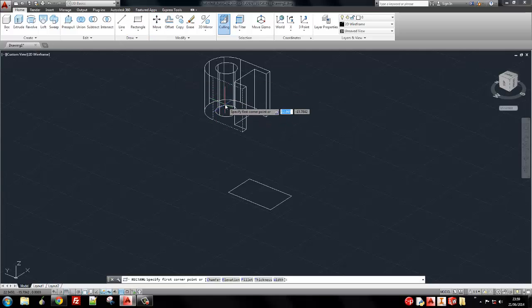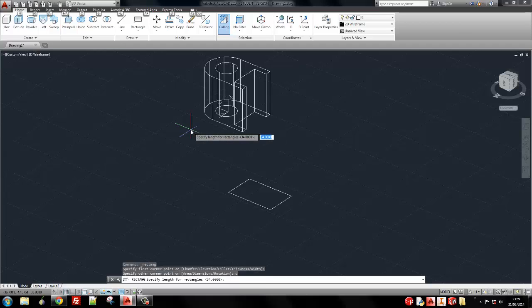Okay. It's not able to create anything that goes in the Z direction, because there is no Z direction as far as it's concerned. It only understands two-dimensional geometry when you're creating two-dimensional geometry, which makes sense when you say it that way. So what we're going to do is sketch onto this plane. Same again, rectangle. There we go. And dimensions. And look at that, it's already remembered what I had last time around. So 34 by 54. And we'll put it there.